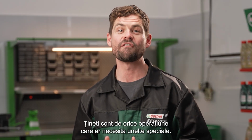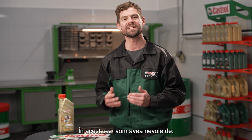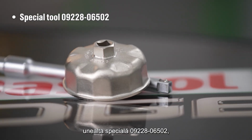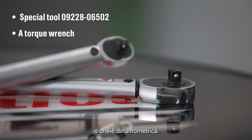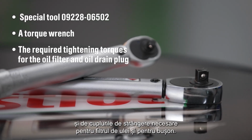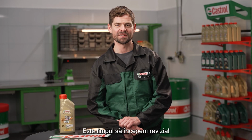Take note of any operation that would require special tools. In this case, we're going to need Special Tool 09228 06502, a torque wrench, and the required tightening torques for the oil filter and oil drain plug. Time to get started on the maintenance.